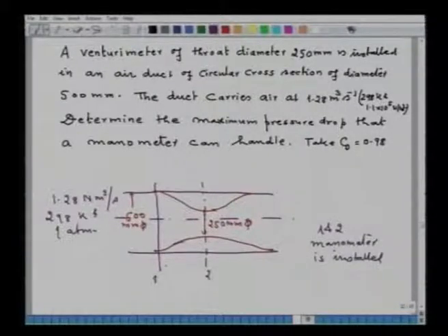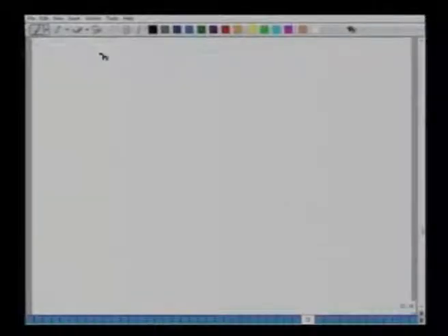We know the equation, because there is no difference in the equation that we have obtained for mechanical energy balance. Though we have said it is for the orifice, in fact it relates the diameters, that is the pipe diameter and the diameter through which the flow passes. So, the same equation will be valid. So, M we know is equal to K y A0 square root of 2 rho P1 minus P2, that is our equation.